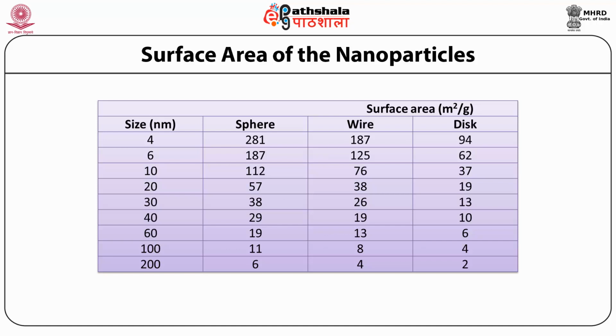The data tabulated above represent minimum specific surface area in the sense that for the particular mass or for the particular volume, a spherical shape has the lowest possible area, and for the particular linear mass density or mass per unit length, a wire of circular cross section has the minimum possible area.